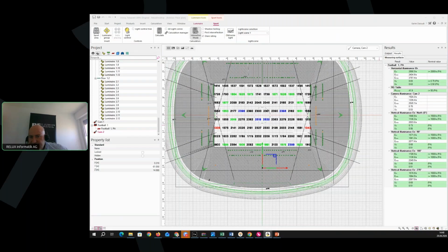Also, please guide about the shadow calculation. Of course, after you have finished this calculation, you can still run the real calculation, because the interactive mode is considering only the direct fraction of the lighting calculation. You can still add the first interreflection of the light towards the surfaces, and also the shadow testing. For instance, the shadows of the luminaires are also considered.